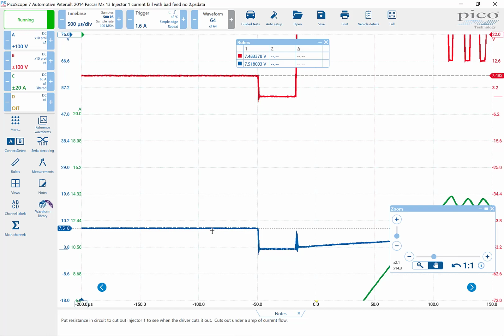If you see that, that's a good sign at first, because that tells you that you have continuity through the coil of the injector. But if you see a way lower voltage on one side than the other, and it's logging a code for open circuit, and you're at the closest test point you can possibly be at that injector, that is telling you you've already got high resistance in the injector. You need to swap out an injector, plain and simple, okay?